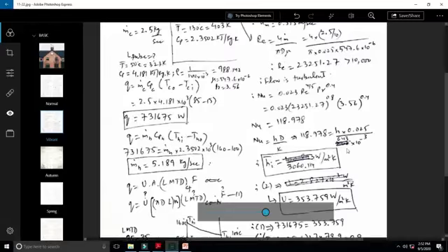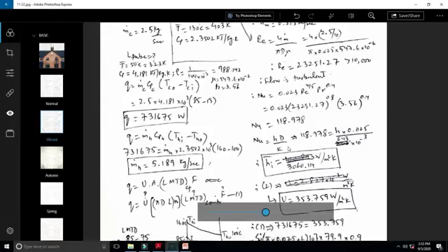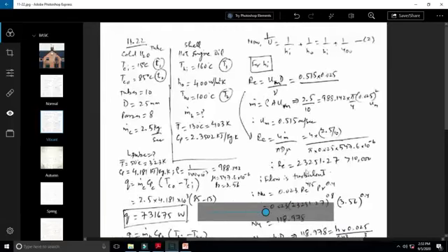Therefore it is 643 exponent minus 3. So we get HI as 3060.114. Kindly note that this K is not the K of the material, rather this is the K of the fluid which is flowing over the inner surface, meaning K of water. That is why we have referred to the property table of water to find the thermal conductivity of the fluid.